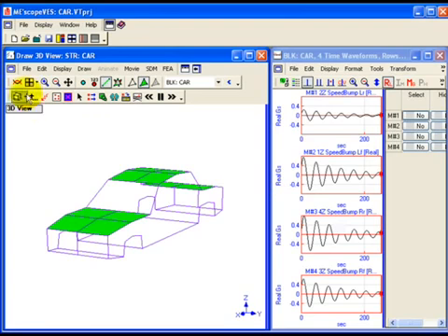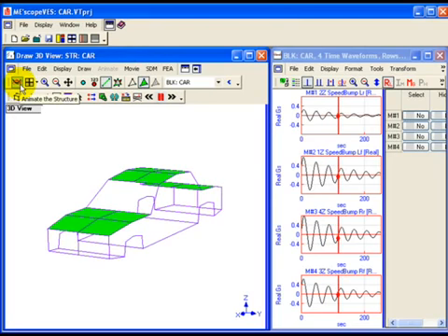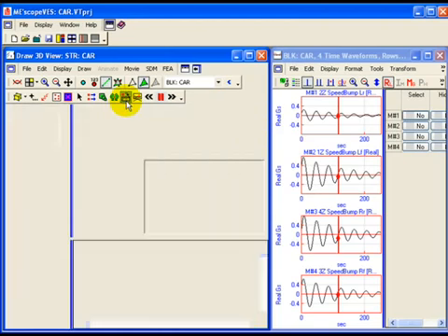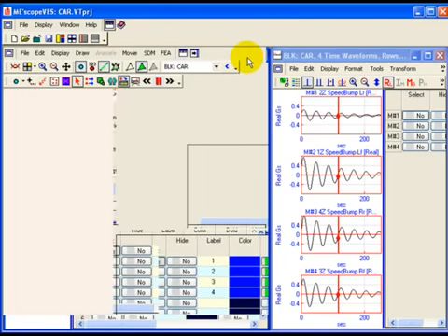Execute Draw, Animate in the Structure window to start sweep animation from the Data Block window. Notice that only 4 corners of the car are animating. These are the points where measurements were made. To examine the measurement axis, execute Animate, Draw in the Structure window to stop the animation. Execute Draw, Animation Equations, Equation Editor to display the Equation Editor tabs above the point spreadsheet.